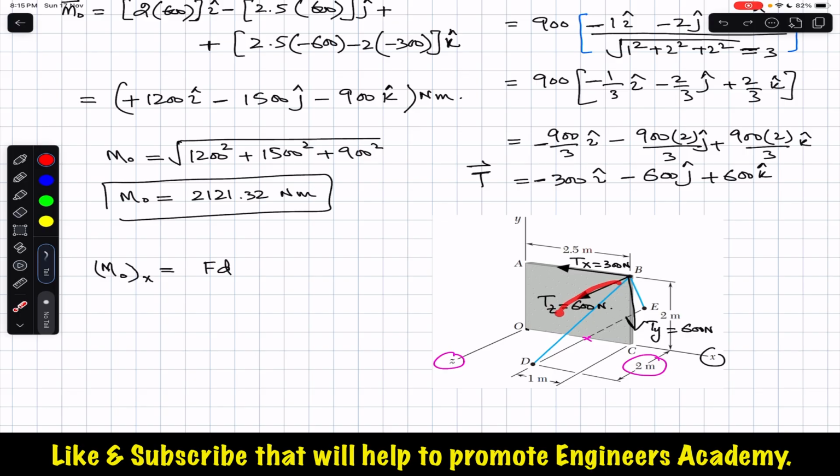It can only rotate this wall about the x-axis in this direction. If we look from this side, then this is the counterclockwise direction. If I curl my right hand fingers in this direction, the thumb will point out in the positive x direction. So this means that this Tz is producing the counterclockwise moment about the x-axis.